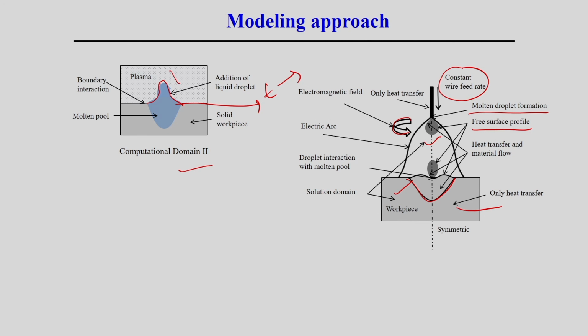So, if you look at all these things, making them a single domain and analyzing all of them together is really complicated, very difficult or almost impossible. So, rather we can divide into different domains, and then do the analysis, and of course, once we have different domains, we need some strategy for how to interact from the thermal model to the fluid flow analysis, or how we will interact the magnetic field with the fluid flow field.